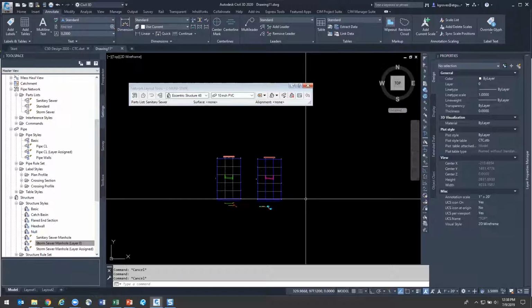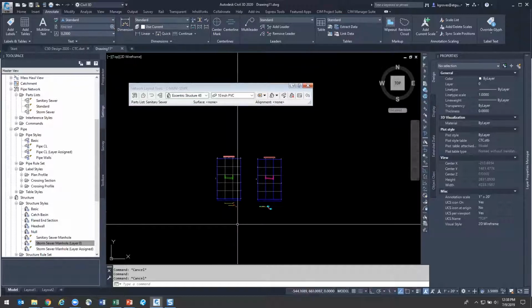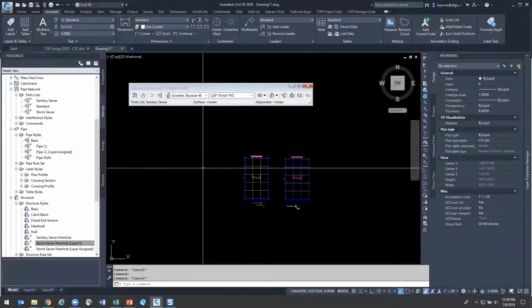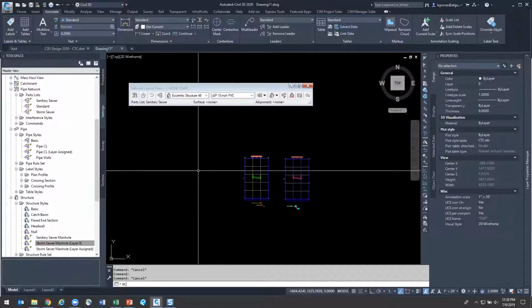And so this is the iteration process that we're gonna go through. And we're gonna do this inside of our main template, or sorry, inside of our test drawing. And now that we've got that for my purposes today, we'll call this set up and ready to go. It's time to import those things back into the main template. So how do we get the layers from one drawing to another? Yeah, that's right, Design Center.